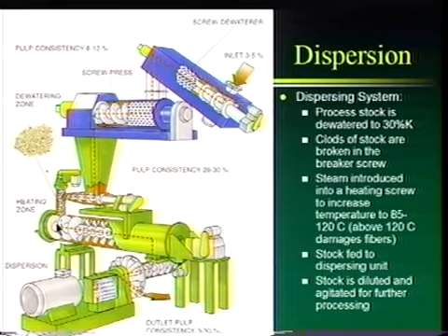It will go down into a heating zone. This heating zone is going to have some agitation here, and we will introduce steam into this pulp. Okay? And the clever thing is that we're adding the steam to the high consistency pulp, not the low consistency pulp, because we want to conserve our energy, and we don't want to be heating up water. We want to be heating up the fibers and the contaminants. Well, we really want to just be heating up the contaminants, but the fibers must be heated up also.